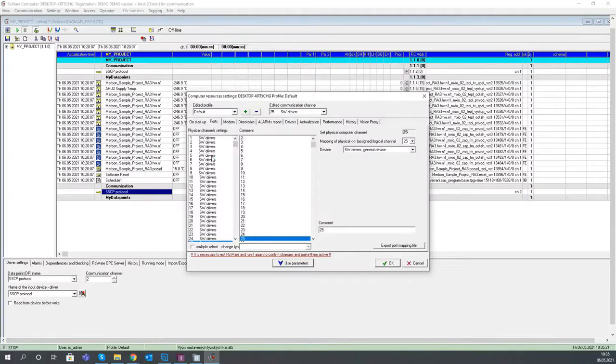So why not optimize the channel list according to the number of really used PLCs? Mostly about 10-15 is okay for a middle-sized SCADA, but if you need, for example, a drugstore chain or supermarkets, banks, or whatever, which have several hundreds of units or branches, you may have up to 400 channels here.